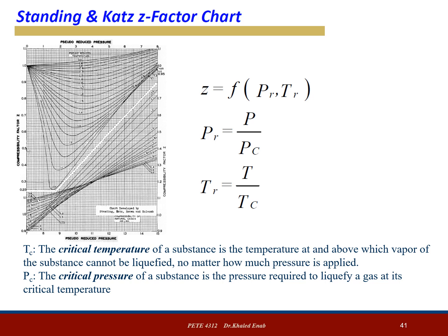So in this case, if you are at 10 here, the example I gave you, and 1.2 will be somewhere down here. So our compressibility factor will be here, at 1.2, somewhere in here. Okay, we'll have more practice in these later. But the one that we did earlier, mistakenly, this one would be correct if my pseudo-reduced pressure is 3.2, not 10. So make sure to separate the bottom part from the top part. Okay?